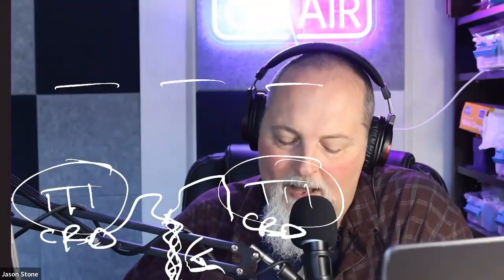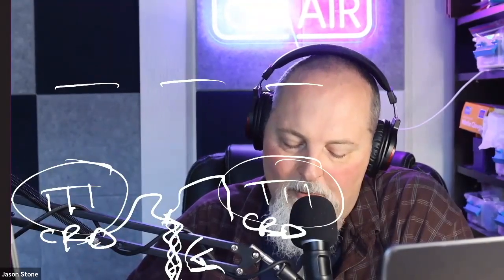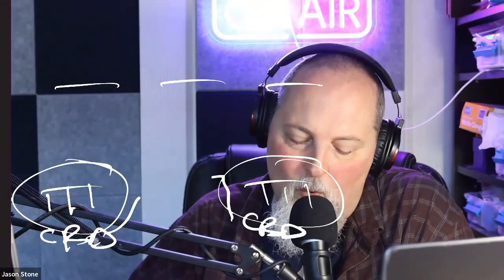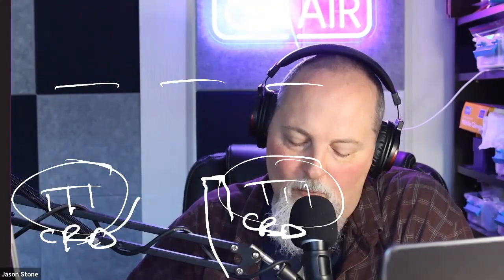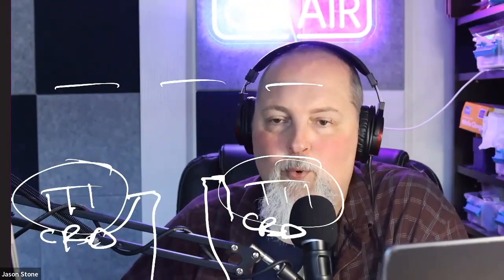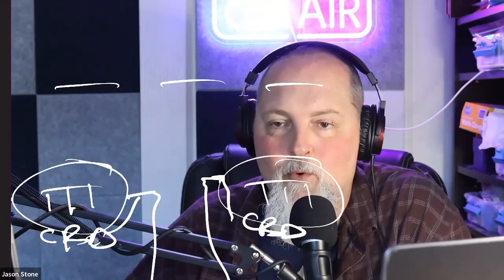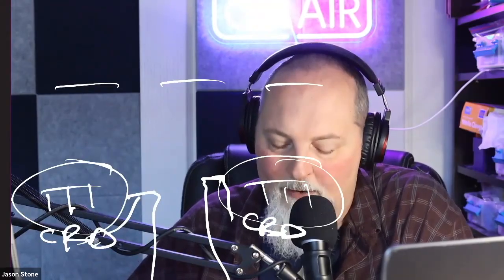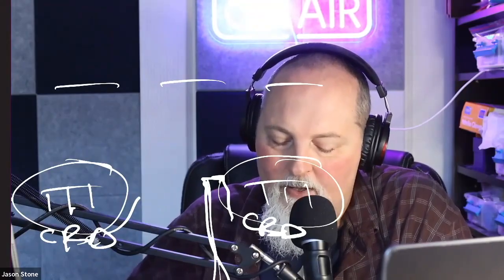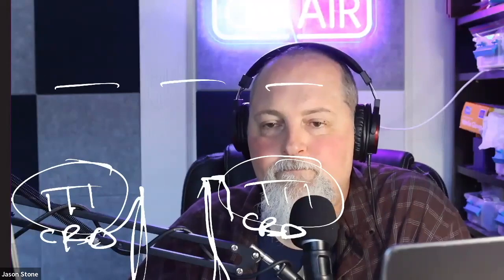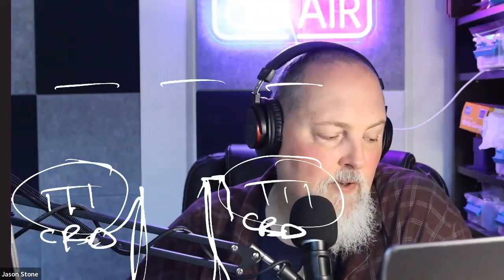Well, we have now what we call divisional separation. We're required by law to route these cables, all the wiring for these things, through different pathways, through different rooms, through different hallways, divisionally separated. We have to keep it completely separate so a fire in one spot doesn't affect the other one. And that's the divisional concept.